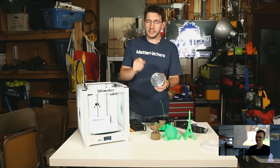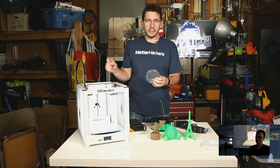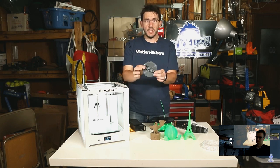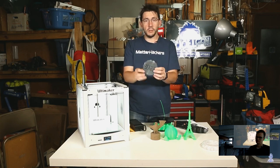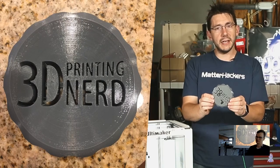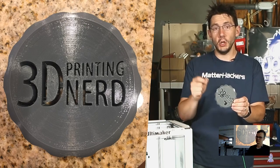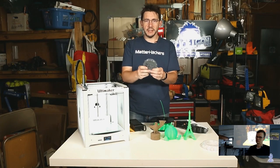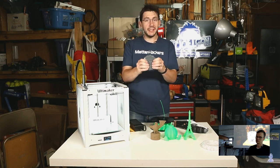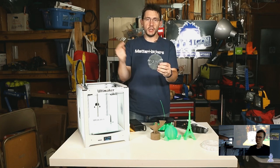ColorFab released a flexible NGen material, and usually flexible materials are hard to print on a Bowden style extruder, but not the NGen flexible. And here's my little maker coin that I had designed in Fusion 360, and it turned out great. Word to the wise though, it sticks like crazy. They recommend BuildTak, and it stuck to the BuildTak like you wouldn't believe. I highly suggest you check your settings and you slowly remove it from the BuildTak. But this is incredible material, and I've got some cool videos coming up about it. But until then, check that out.